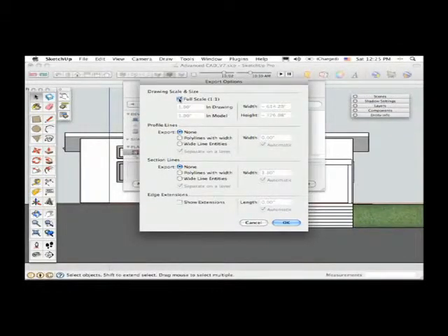If you're working in a CAD program like Vectorworks or some other app where you're drawing in your CAD application at a particular scale, maybe you're drawing at 1/4-inch scale or 1/2-inch scale, then you have the option to uncheck the full scale checkbox and instead tell SketchUp what scale you want to export the drawing at. So in this case, say you wanted to export the drawing at 1/4-inch scale. You would type in 0.25 inches in the drawing equals 1 foot in the model. The SketchUp model is always going to be at 1-to-1 scale, so you can kind of work backwards from there. 1/4-inch equals a foot scale means that a 1/4-inch in your drawing equals a foot in the model.